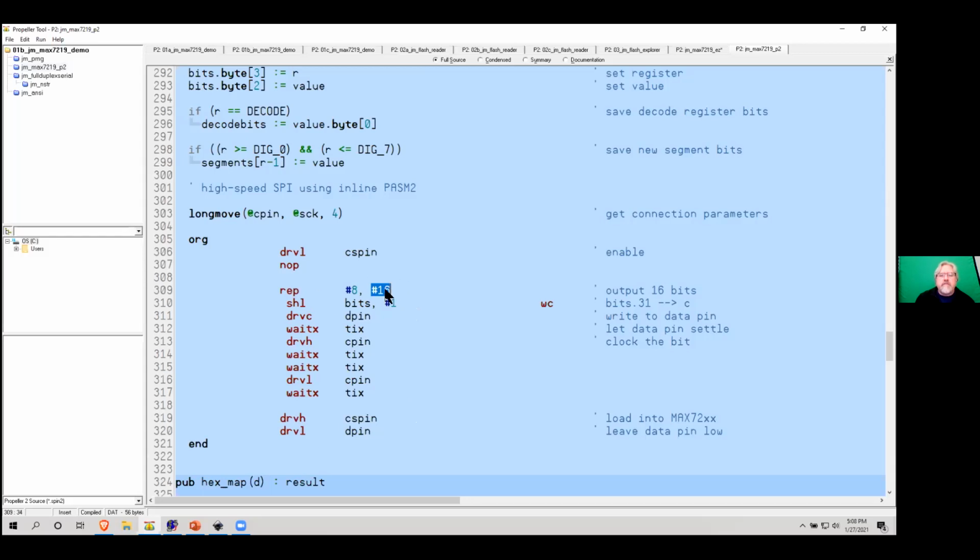And you can, of course, have a variable here. I don't know that that'd be wise to have it here, or if you even can. But in this case, we know we're sending 16 bits. So that's what we're doing. Now, this is doing the equivalent of that rotate. Before I've set up the bits just the same as before. So my first bit is in bit 31.